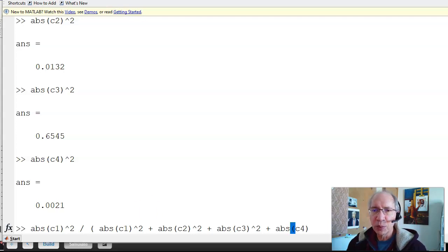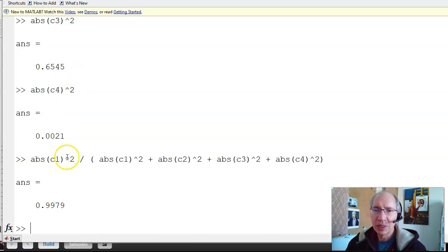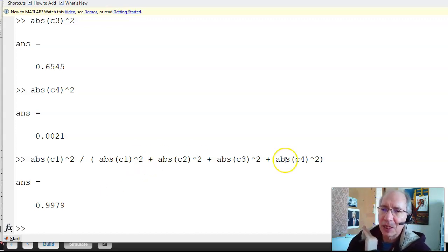It should be 1/2 that, 1/2 the magnitude squared. But when I take the ratio, the half will cancel. The net result is this DC to AC converter has 99.79% of the energy in the first harmonic. Roughly. I should take this out to infinity.